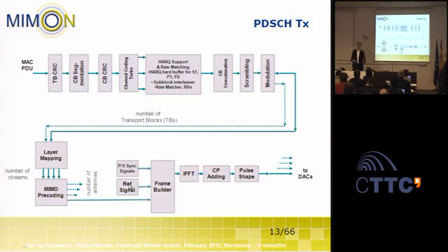We include the broadcast channels, the control channels, and also the reference signals and the synchronization signals in this radio frame. At the output, we basically perform a transformation back to the time domain. So our frequency signal, our OFDM signal, is converted into the time domain with the inverse FFT. The cyclic prefix is appended to ensure that inter-symbol interference is avoided. We have pulse shaping, and then this is transmitted from the 4 antennas. So this frame building process is performed 4 times for the 4 antennas. This is then transmitted over the radio channel.